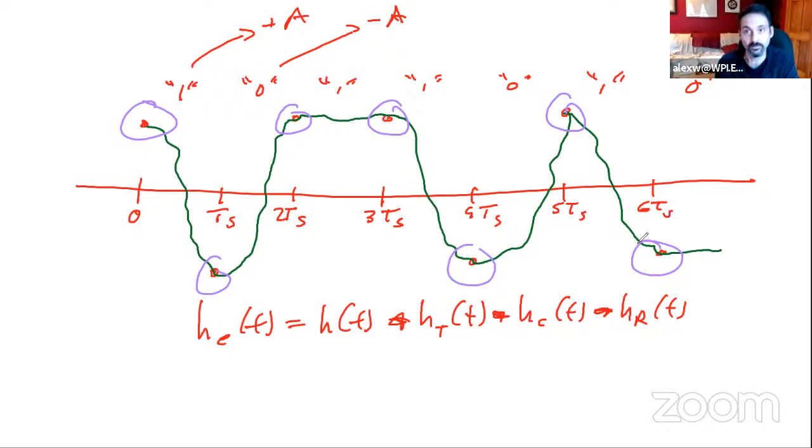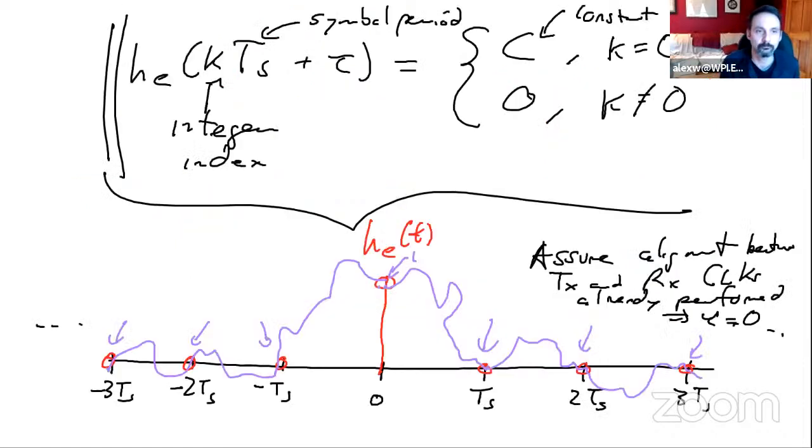because what will happen is, when my receive radio gets the signal, it's going to first of all digitize the incoming analog signal. So it's going to sample very specific instances. That's why tau is actually kind of important, in order for the two to be on the same page, for them to be synchronized in time. Once you know exactly where the sampling instances are, going back to the Nyquist pulse shapes, going back to this very important rule, all right?